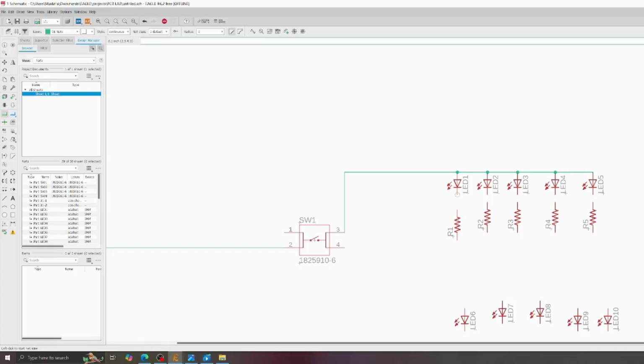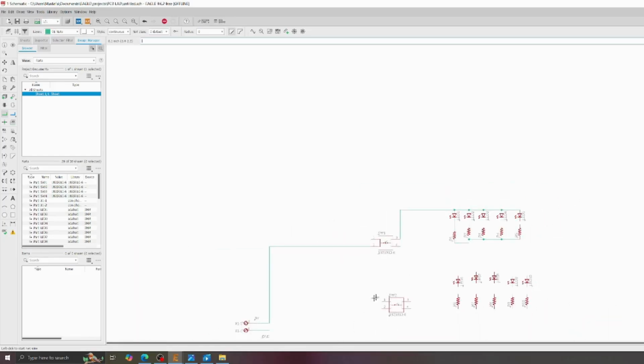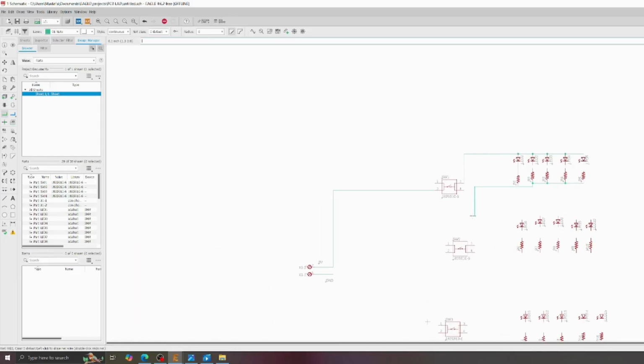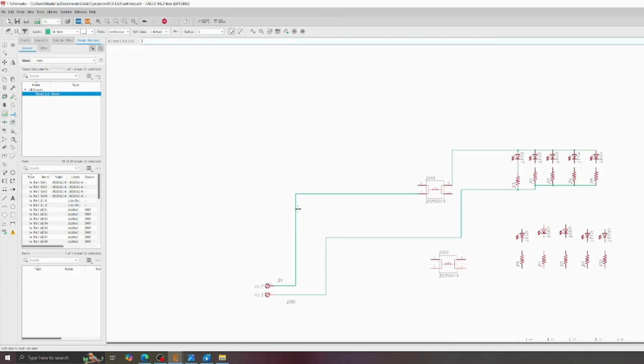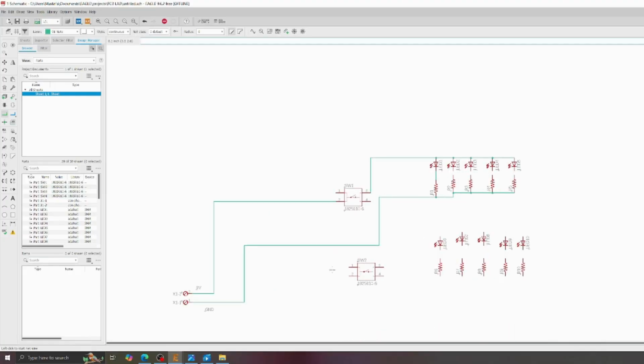So next, we're going to take, like we did in our Tinkercad, connect 1 here, and then we're going to connect to that one. That one is going to then connect to all of these. And then lastly, our resistor is going to connect all the way back to our battery. That's going to say, do you want to merge N, whatever name you gave it, into ground? Just click yes, and now it's connected. This circuit is now working.